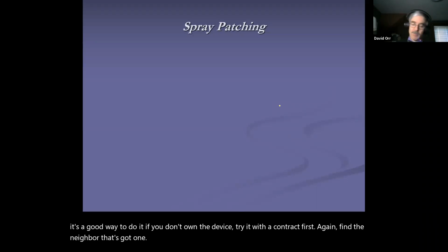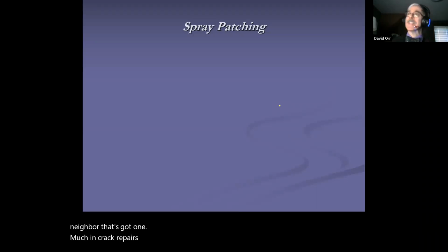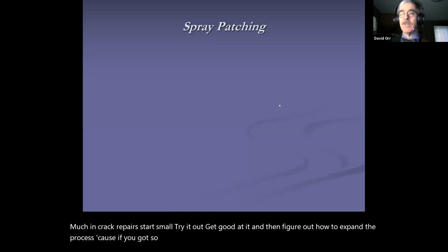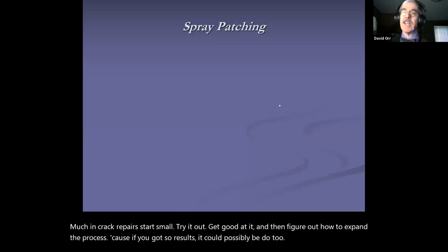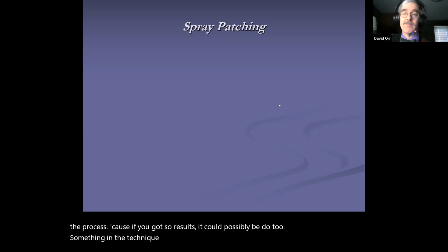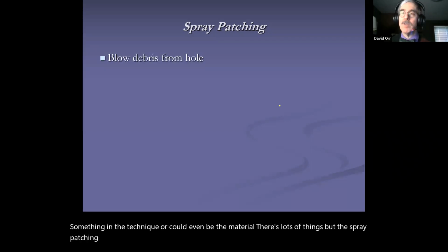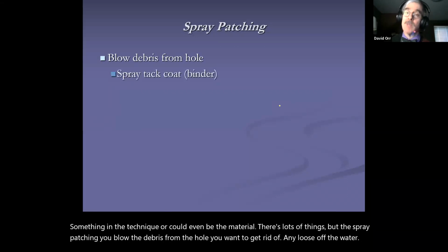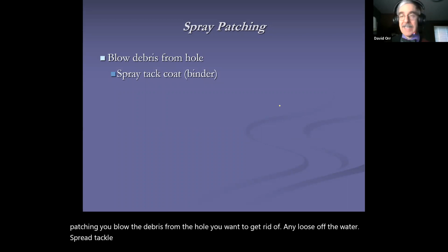Much like in crack repairs, start small, try it out, get good at it, and then figure out how to expand the process. Because if you got so-so results, it could possibly be due to something in the technique, or it could even be the material. There's lots of things. But the spray patching, you blow the debris from the hole. You want to get rid of any of the loose stuff, the water. Spray a tack coat.